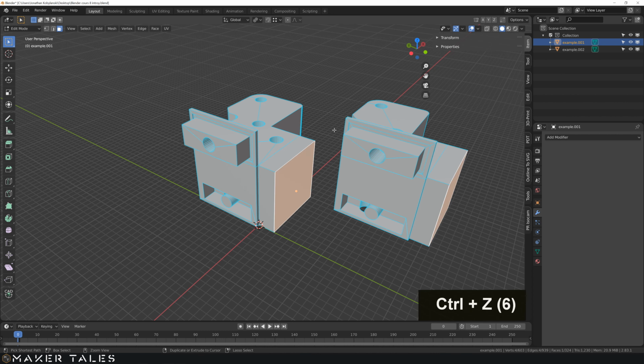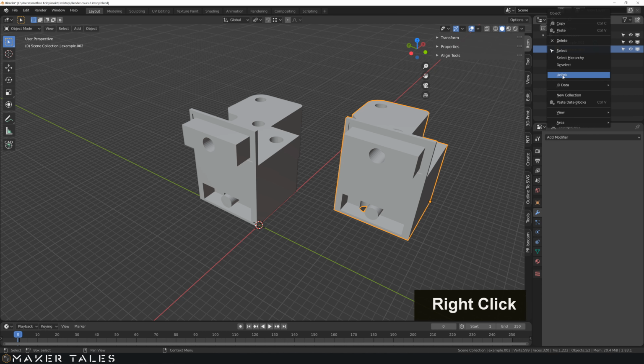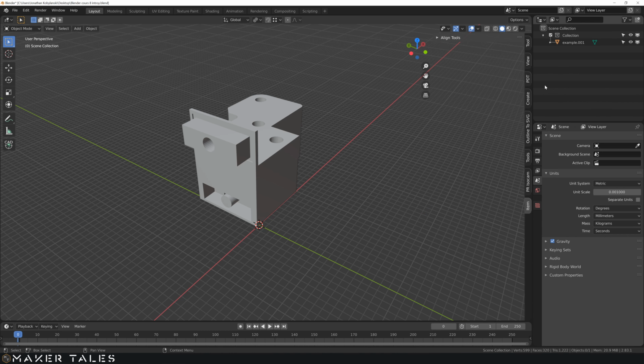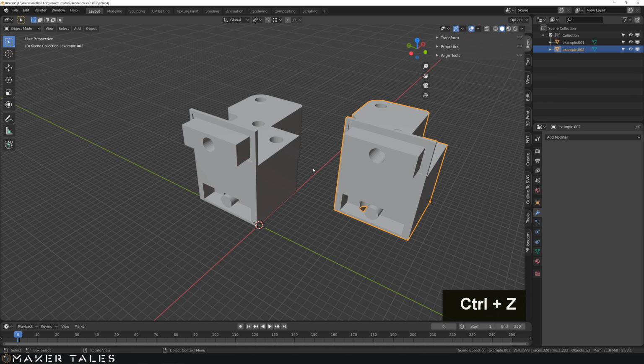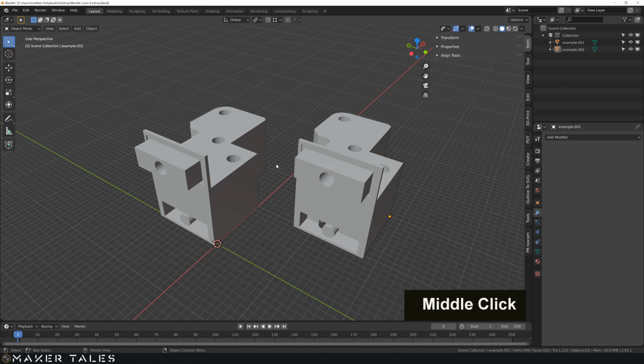Alright, let's then do a couple of times. Now that we know how to create a linked duplicate, let's find out how to unlink this duplicate. So it's one of these more hidden features. I wish it was nice and easy just going right click here and unlink. However, you're going to see that this here deletes the object. Well, it hasn't really deleted it. It's to do with how Blender works with something called object data. So an object in Blender is like a collection of information, and it isn't really an object. It isn't of itself till you set it to be.